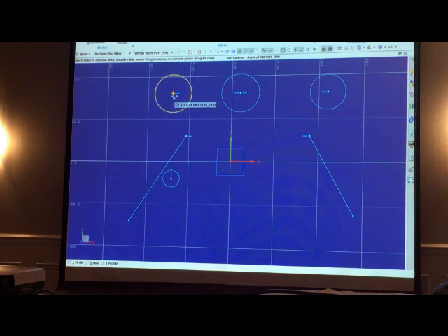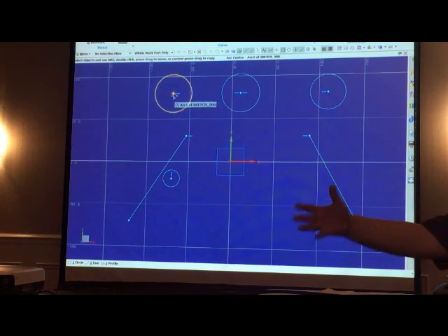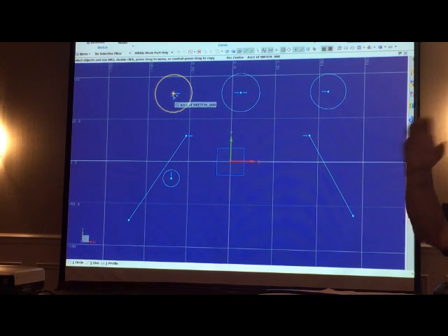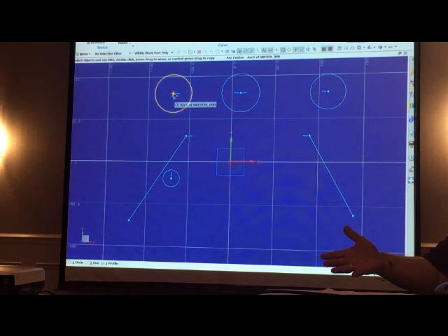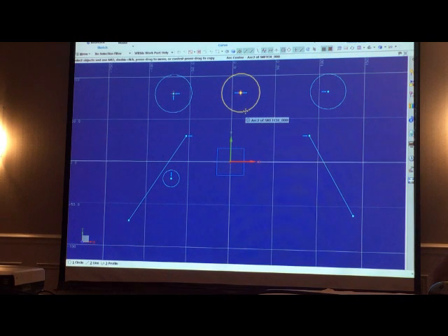Now, you can do this today, but you've got to draw extra geometry. Draw a line, constrain all the circles to be on the line, and then probably turn the line into a reference curve because you don't want it part of your profile. What we've added is a new constraint called horizontal and vertical alignment. Don't confuse this with horizontal and vertical lines. That's different. This is simply the alignment of points. It can be the centers of arcs, endpoints, midpoints. Any point can be aligned to another point, whether it's a point or a virtual point.